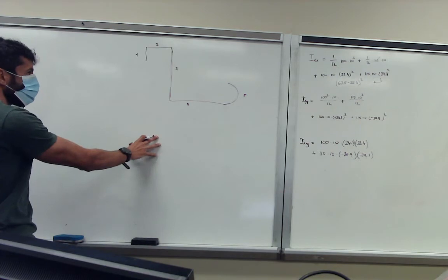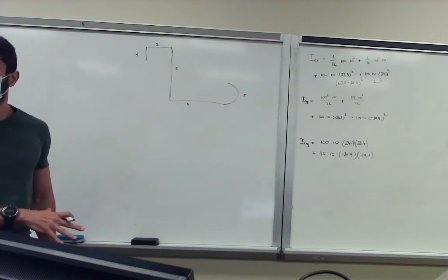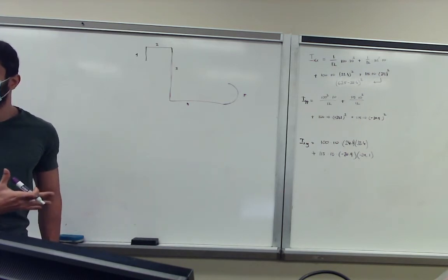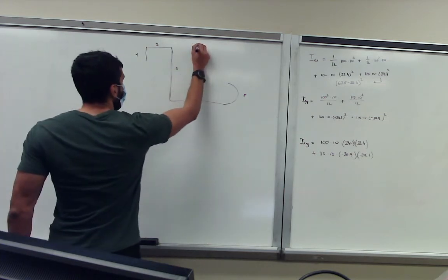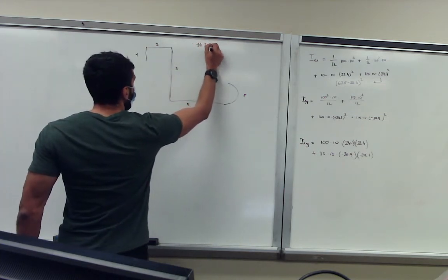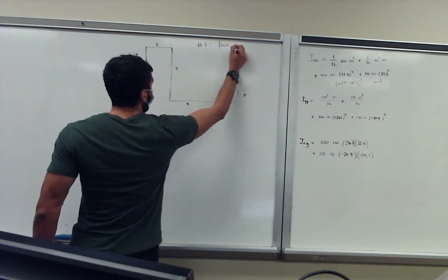So the first step is, in this case, find the centroid, because your moment of inertia would be focusing on your centroidal axis. Okay? So in this case, step 1, find centroid.